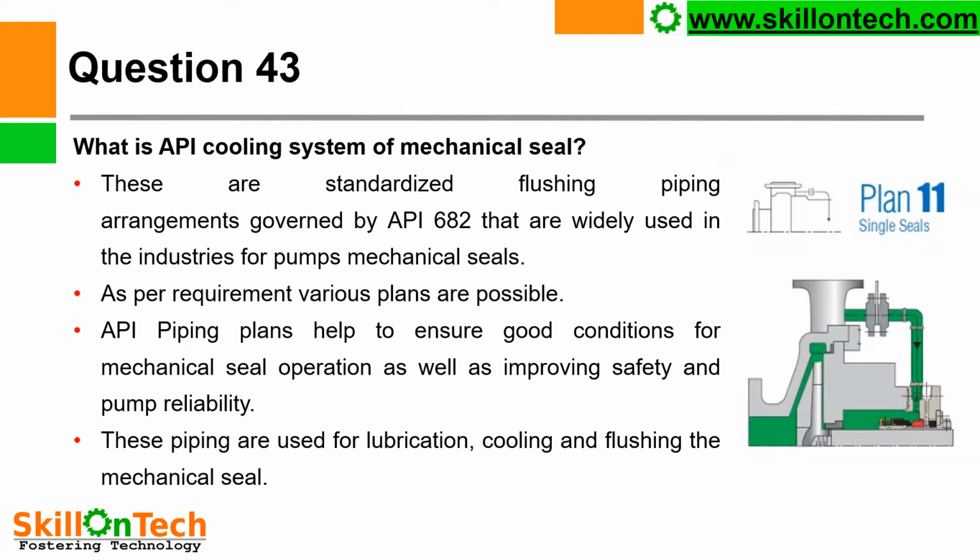You can see in a picture where plan 11 is shown as per API 682. A discharge pipeline of the pump has been given a branch pipe for providing cooling and lubrication to the mechanical seal.